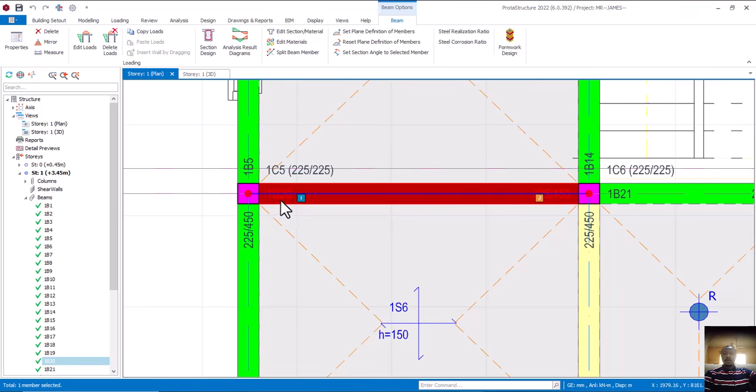At I, this beam stops on this particular column. There's no continuation of beam. Is that okay? So this particular one becomes the beam end condition. And we said, based on the principle, that beam end condition is equal to 0. Is that okay? And since it's 0, it means there's no moment.